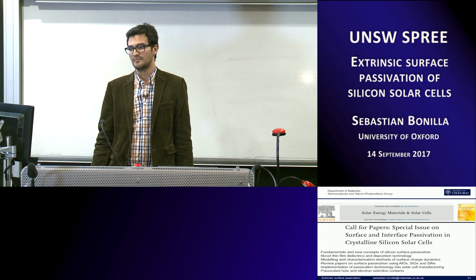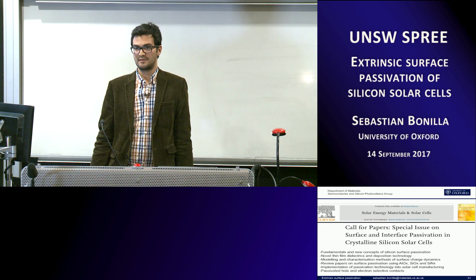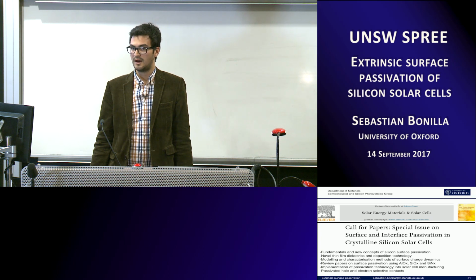Okay, next question. Your amorphous oxide nitride stack, do you have any insights as to where your charge is sitting in that case? Yes. We think the charge sits at the interface between the oxide and the nitride. We're fairly confident of that.